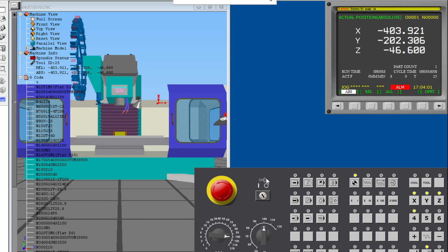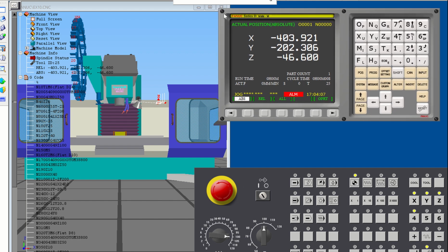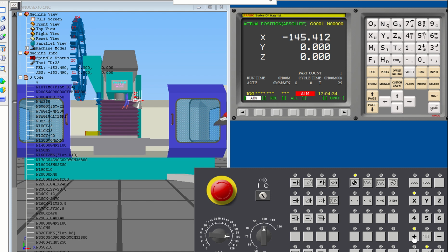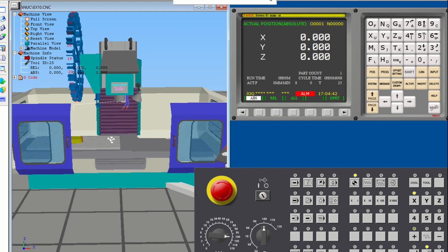So I want to go to this machine, this controller, and do a simple home. Then you will see what it means for us to understand these configurations. Step by step, let me show you. Ensure that you release the emergency button, and then click the reset button. From reset, click the home button, then click the Z button, then click positive. The machine goes home. It must display 0. Click on the Y-axis, reference the machine. Mine is referencing; I would pursue the problem if it were not referencing. Then the Y-axis also references. It goes home. So this is the machine.